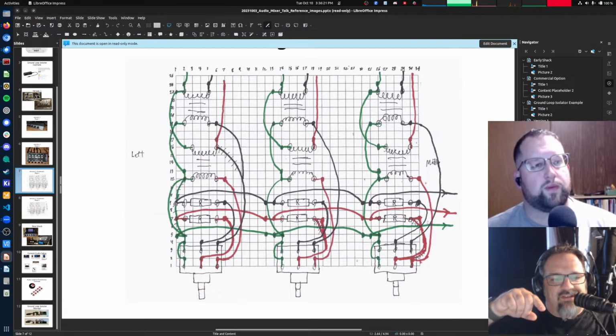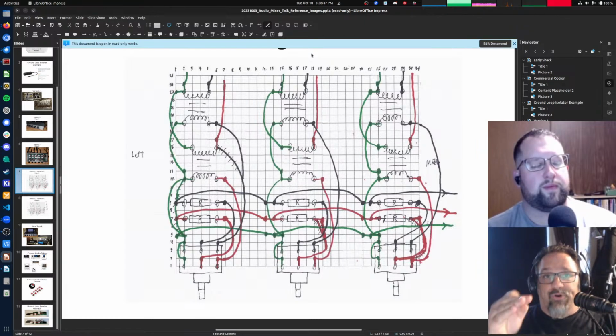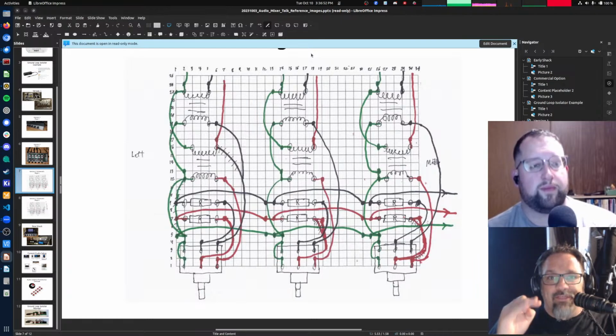The problem is, it also goes through this common bus, through this 1K resistor, back into the wiper of this potentiometer, and through some amount of resistance here, out through the input into the isolation transformer, back out the other side of the isolation transformer, and into the output of your Flex. Right? We're going in through the output.